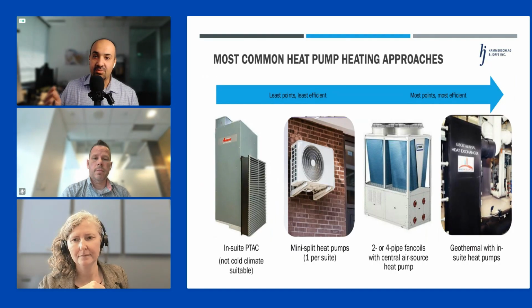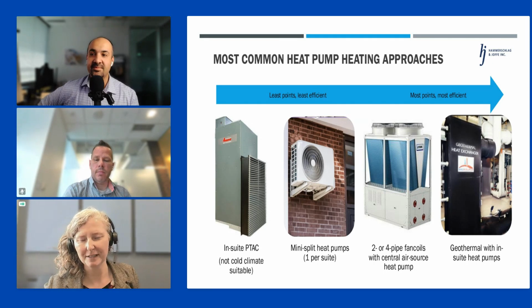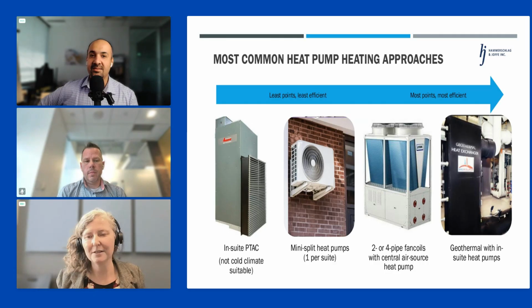And I can tell you, based on rule of thumb, and by all means, Kara and Scott, correct me if I'm wrong, we've found that lower than 30 units, it's really hard to make the numbers work for these types of bore fields, but 30 is probably roughly where the numbers start making sense to introduce that type of system. That is a perfect summary. Yeah, I've often heard 100,000 square feet is the magic number where all of the drillers will talk to you, and I think 30 units is a really good lower boundary for where at least some of them will talk to you.